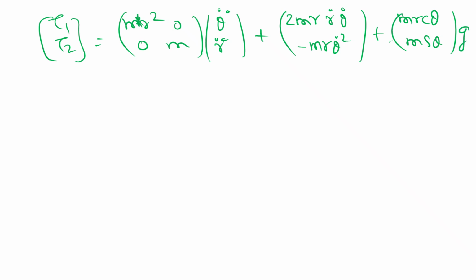So your torque is composed of acceleration. Then this one, r dot and theta dot, is the Coriolis effect, and this theta dot square is the centrifugal effect, and then this is gravitation. So this is the combination of these three effects. So this is the dynamics of the RP manipulator.